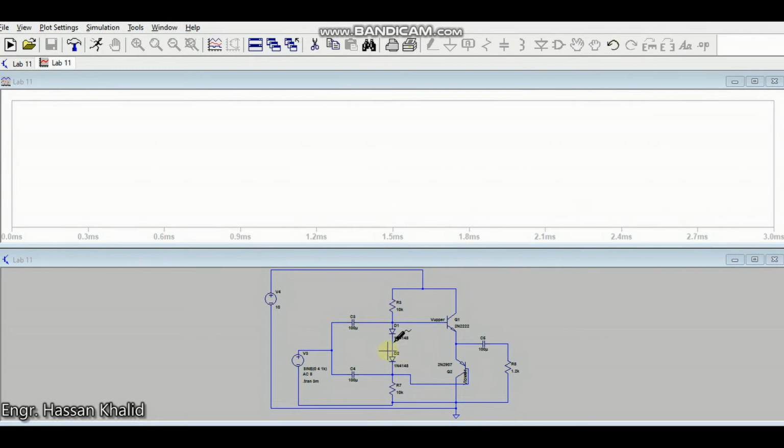Okay, we can now use the basic concept from the previous circuit diagram: if the voltage drop shared by the resistor is not sufficient to cause conduction, then there might be issues regarding the crossover distortion and the change in the amplitude as well. Previously we were supplying 0.77 volts to cause good conduction in the base emitter junction. Now we are using two diodes, and we also demand that they must have an equal amount of voltage.